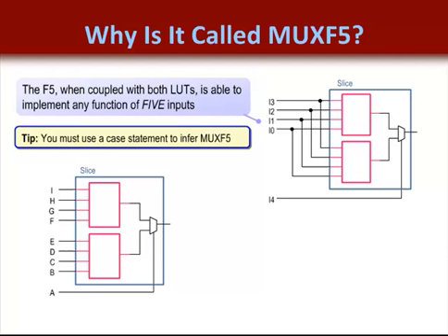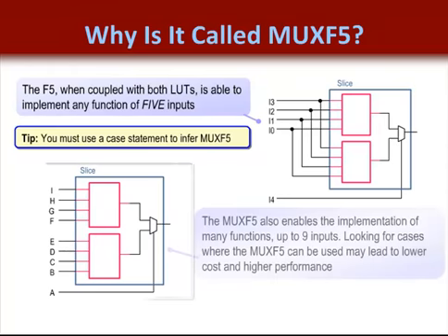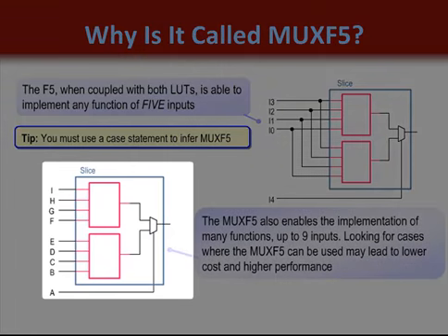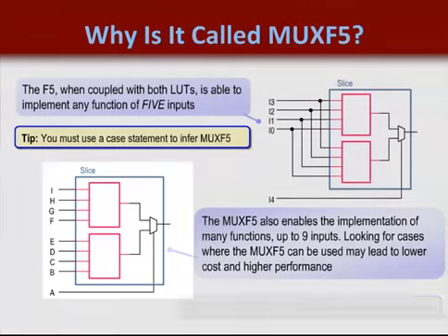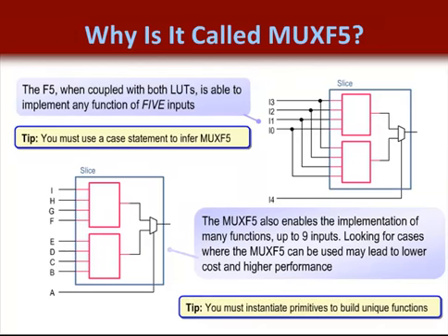Note that while MUX behavior can be inferred in most cases, it will require the use of a case statement in your HDL. The MUXF5 can implement some functions of up to 9 inputs, providing the inputs can be separated into 2 functions of 4 inputs. Unfortunately, not quite as useful as you might think. However, this will require you to instantiate the appropriate MUX primitives to construct your system in this way.